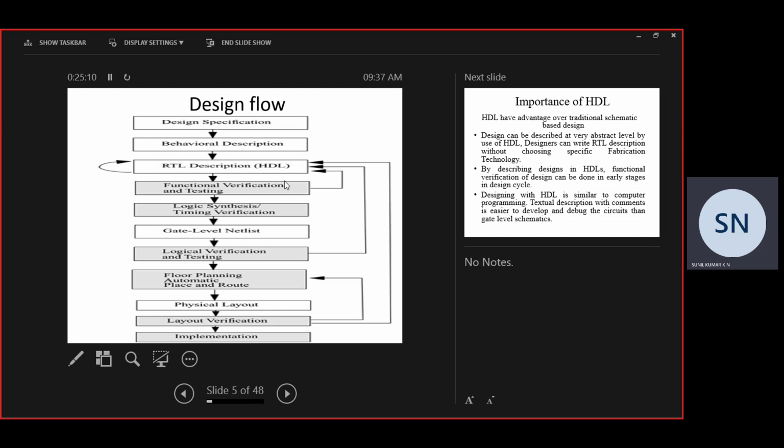So the third case, just the opposite, 1, 0. So this 0 means this will be off, there is no reaching point. This is 1, 0. So this will be off, but since it is on, VDD through this path will come and the output will be 0. So this is also verified. So the last case is what? 1, 1. 1, 1 means both the transistors are on.